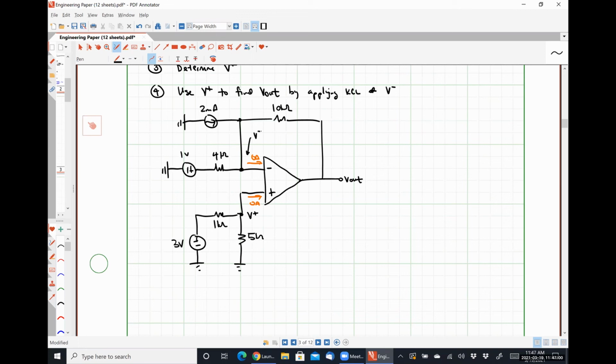So we've already knocked out the first 2 steps. How do I determine step 3, what my voltage present at my non-inverting input terminal is? Voltage division, perfectly reasonable, because we know that no current can branch off and flow through. So based on the ratio of these resistances, what are we going to have? 3 times 5/6, right? So 15 over 6. Easy enough.